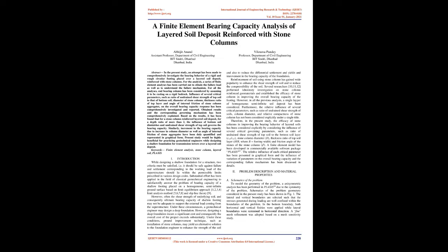However, often the shear strength of underlying soil, and consequently ultimate bearing capacity of shallow footing may not be adequate to support the external load coming from the superstructure. Under these circumstances, a geotechnical engineer may design a deep foundation. However, designing a deep foundation incurs a significant cost and consequently the overall cost of the project exceeds substantially.